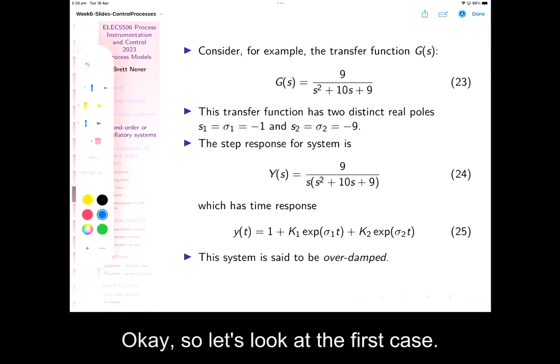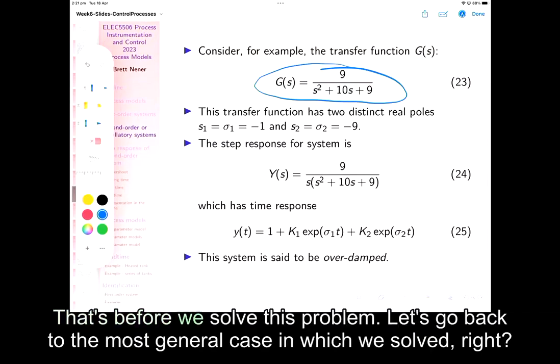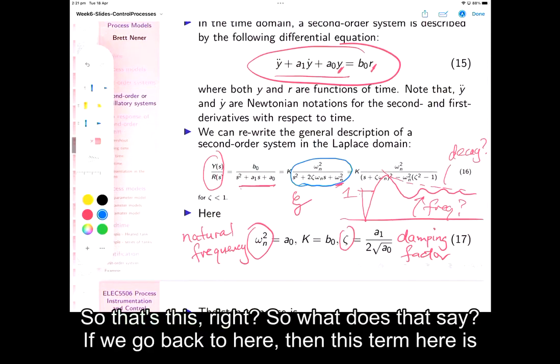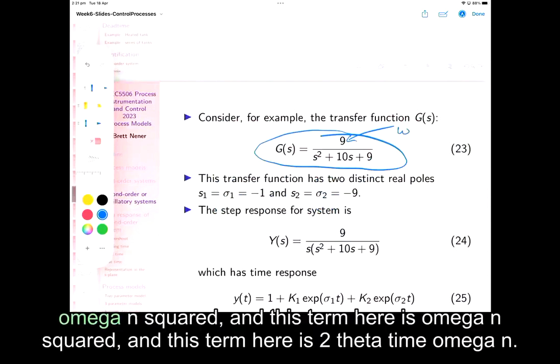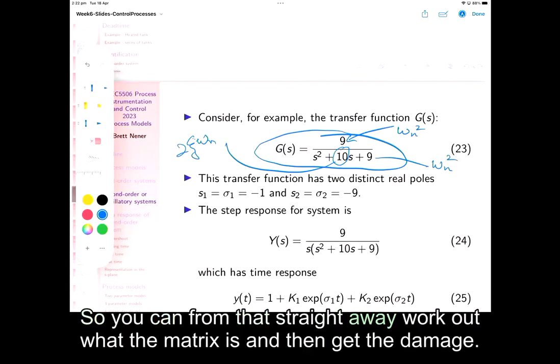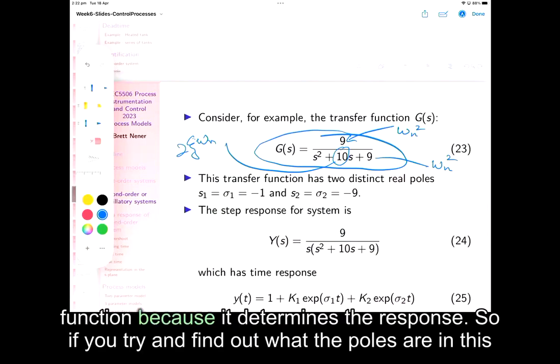Okay, so let's look at the first case. This is the transfer function. Let's go back to the most general case that we solved. This term here is omega n squared, this term here is omega n squared, and this term here is 2 zeta times omega n. So from that you can work out the natural frequency and then get the damping straight away. The denominator in this equation is called the characteristic function because it determines the response.